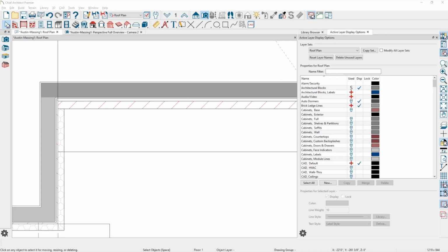If you're going to just want the studs and the outer edge, I think Scott talking about changing the wall definition probably is the only way other than just fixing up something with the CAD lines and putting them on a specific layer that you can toggle on and off.